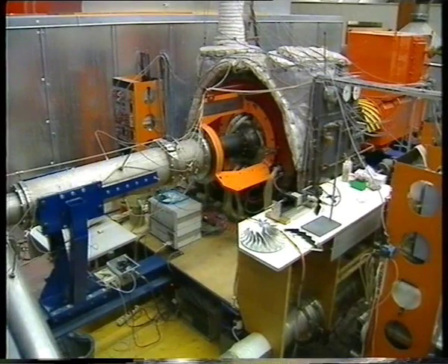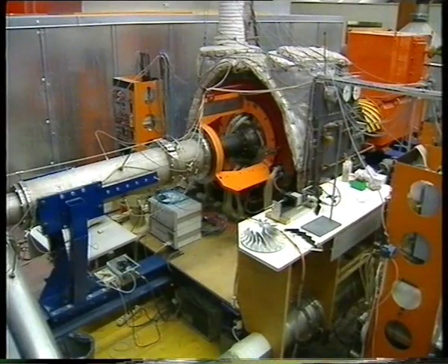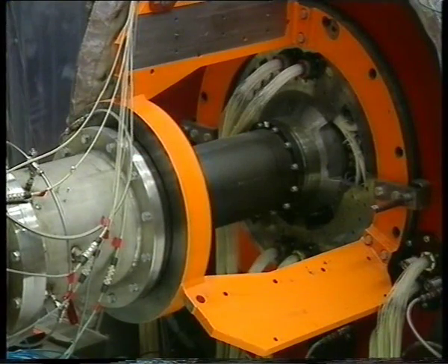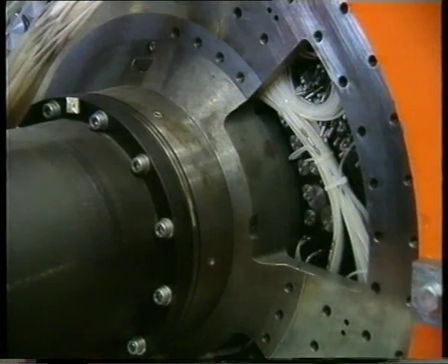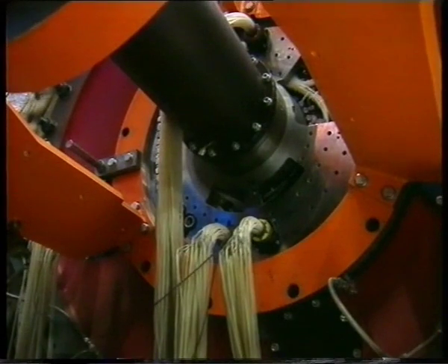Detailed investigations of centrifugal compressor instabilities such as surge and rotating stall have been carried out at the Turbo Machinery Laboratory on a subsonic to transonic single-stage centrifugal compressor. To enable visualization of these unsteady flow phenomena, this air compressor has been modeled with water as the working medium.